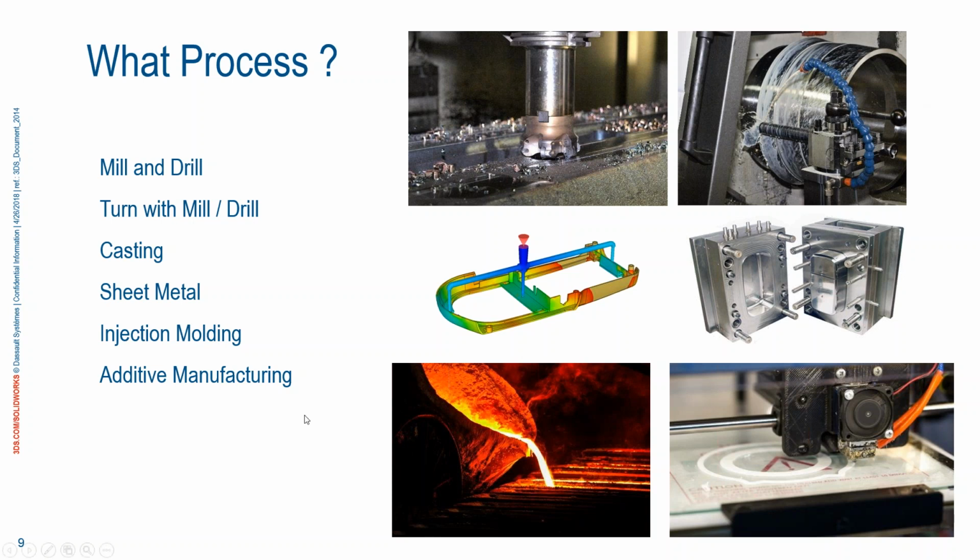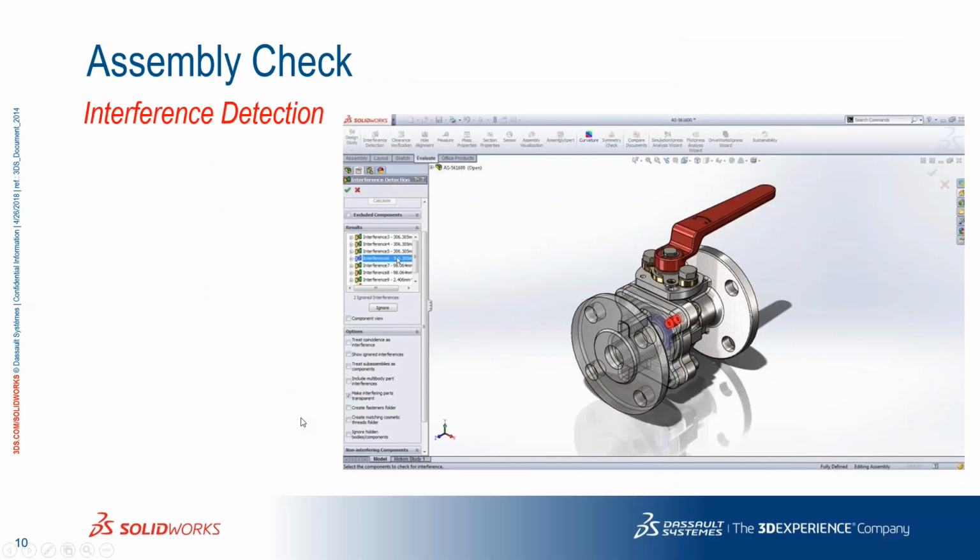And I will go through some areas with some tips and tricks, what to think about here. So let's get started. First of all, the most commonly used, I will say, or the reason when I started with 3D CAD was to do the interference detection with 3D models. This is coming from 2D to 3D. This is the most common way to check your parts and see a value of 3D collisions here.